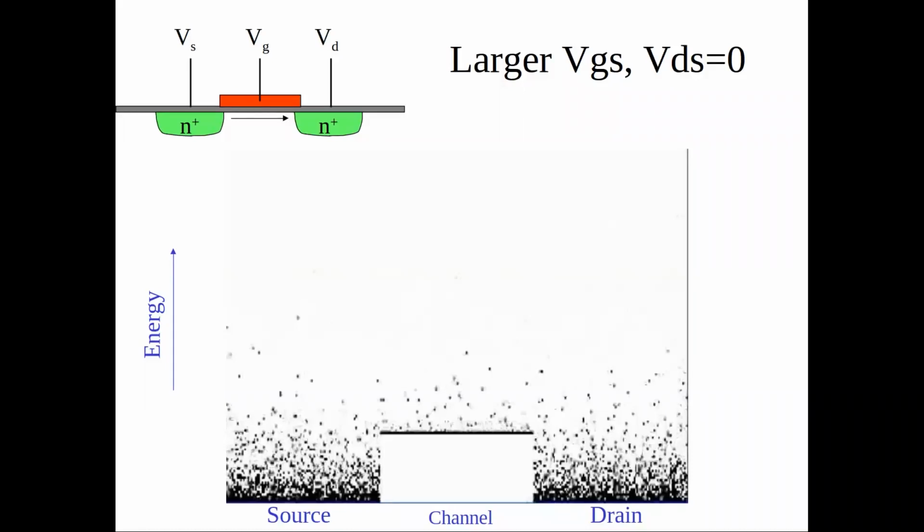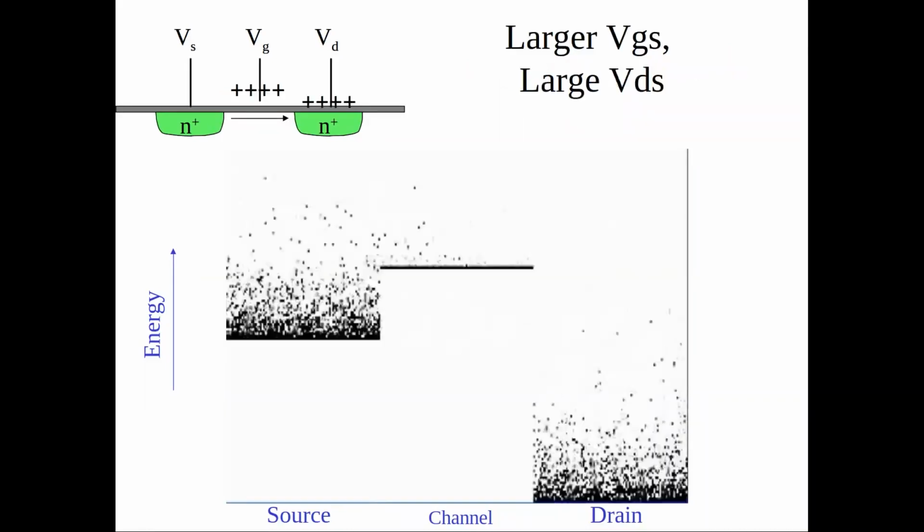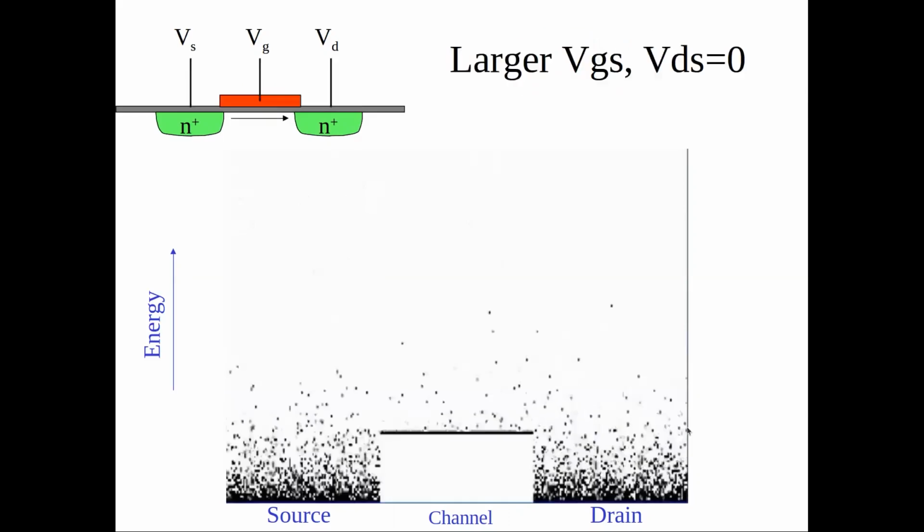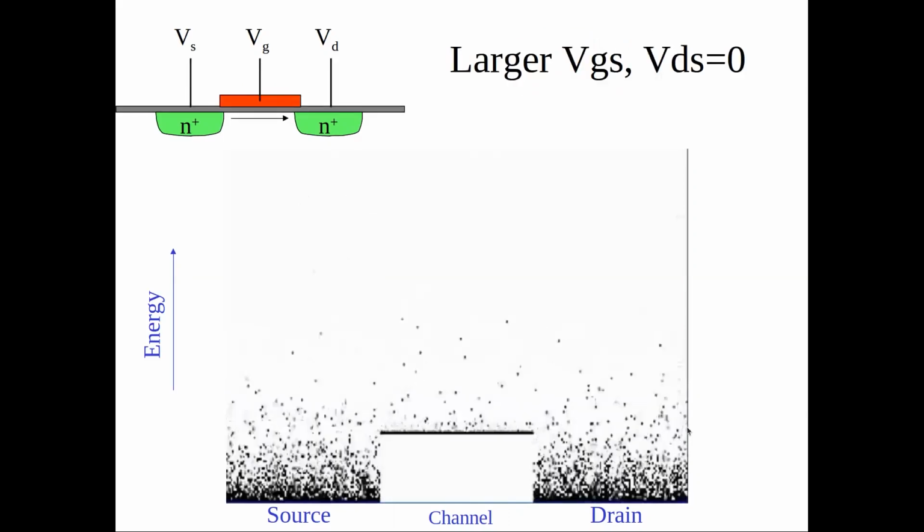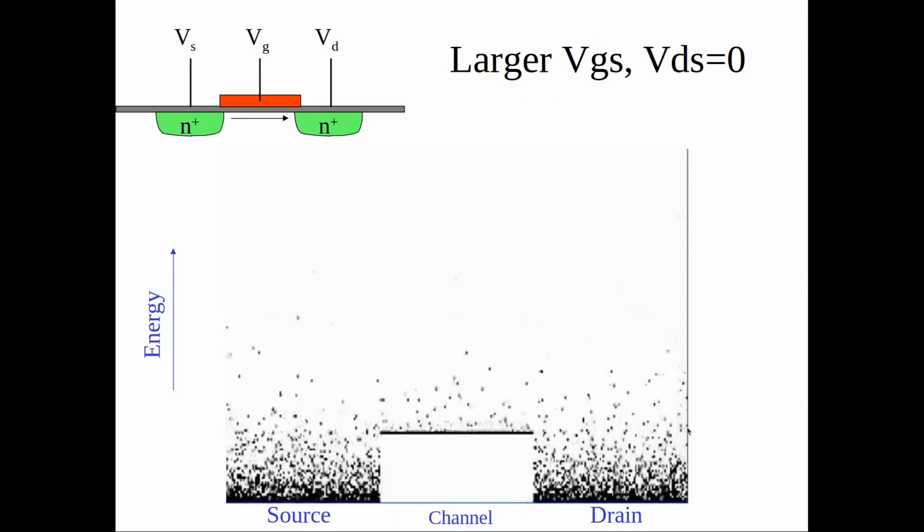No, there's going to be an equation. Let me see if it was in the equations that we saw before. Yes. Just repeat that for NFET. This is NFETs, yes. So the positive voltage is decreasing the energy barrier. For PFETs, you always have to remember it's the other sign, so you should decrease the voltage to decrease the energy barrier. But there will be equations. I will also show you later with the equations that basically describe this.